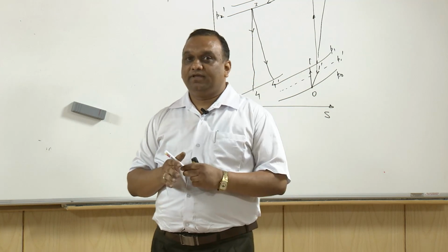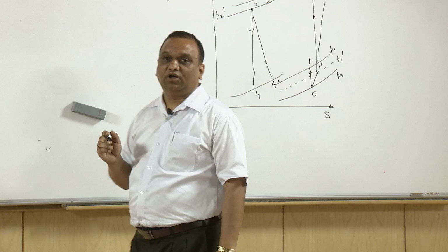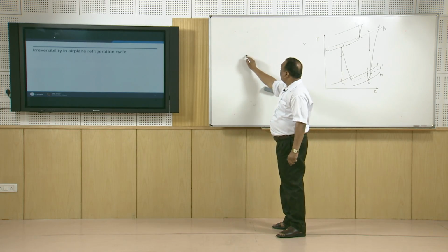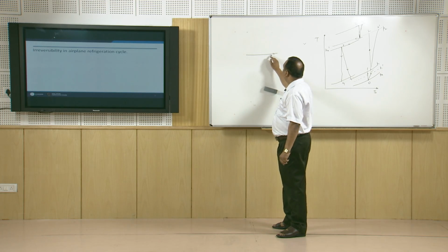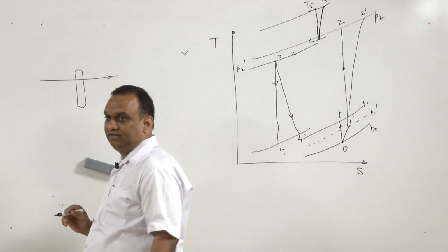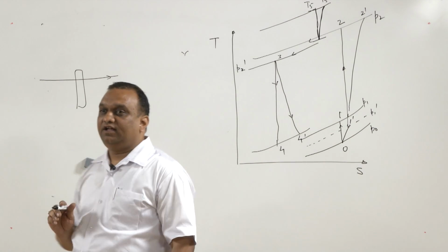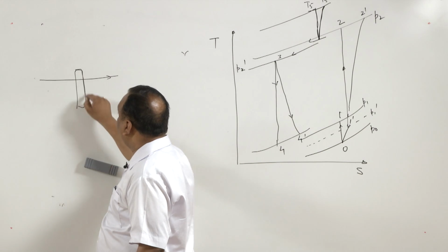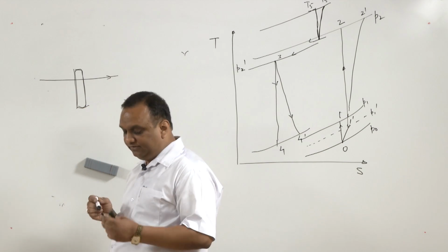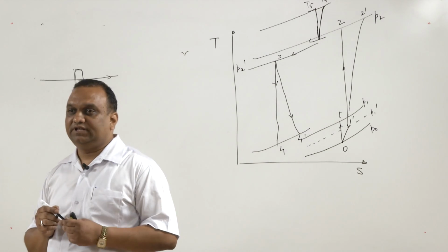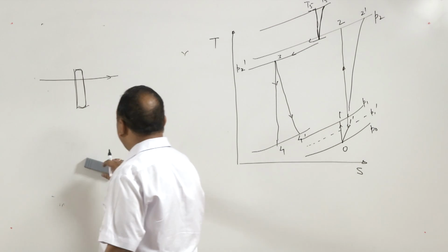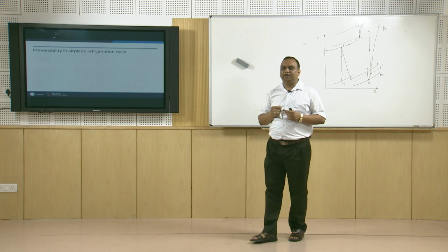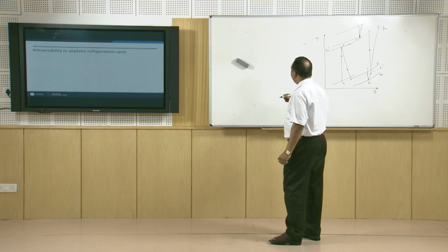The reason being that, let us take the example of an axial flow turbine or axial flow compressor. In an axial flow compressor, there is no change in the direction of the fluid. Fluid straight away passes through the compressor. Since there is no change in the direction of the fluid flow, the losses are minimum. So, highest efficiency is attained with axial flow compressors, and it is always close to 90% or greater than 90%.